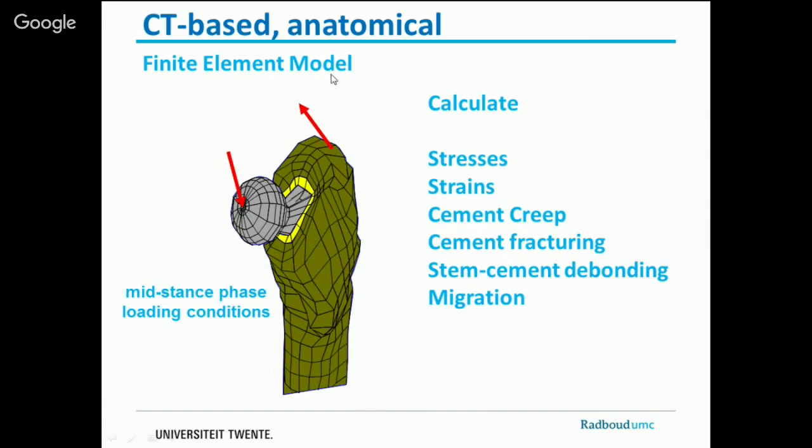Okay, so we have looked at this using finite element models, and we can calculate with these finite element models stresses and strains. We can simulate cement creep, cement fracturing, and we can look at how stem cement debonding, what we just demonstrated, that clinically actually happens, how that all works together.